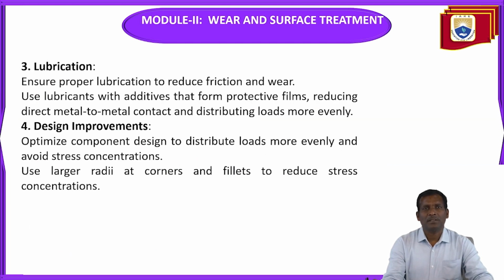In lubrication, ensure proper lubrication to reduce the friction and wear by selecting the proper lubricant and proper lubrication system. You can reduce the friction and wear. Use lubricants with additives that form protective films, reducing direct metal to metal contact and distributing loads more evenly.